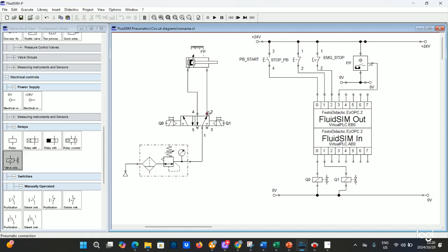Q1 is on, right? That's what's keeping the cylinder. So if I play this, as you can see, air is coming from here to here, right? Which means Q1 is currently on, which means it's allowing air to pass through to keep the cylinder in the retracted end position, right? So when this gets activated, it becomes on. Air has to come in this side, right?